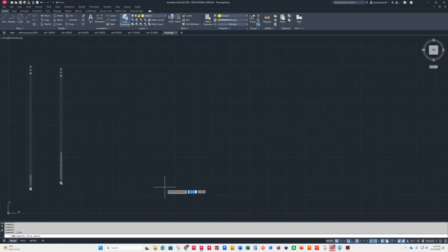If you look at it from this side, the 2 lines become hidden. Well, that's 2. So you draw it from this side, which is the left, you've got less hidden lines showing. So therefore, we're going to do a left side view.